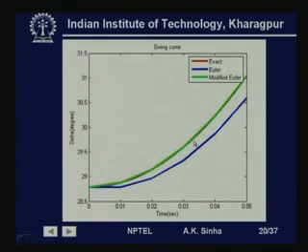So, instead of the accelerating power, which is Pm minus Pe, where we had taken Pe equal to 0 for all this period, Pe now will have to be replaced by this Pe relationship, where the values will keep changing with the delta angle. So, using this we can find out again how the swing curve evolves, that is how the machine power angle or delta angle changes with time once the fault is cleared. Okay, so this is how we can plot the swing curve.